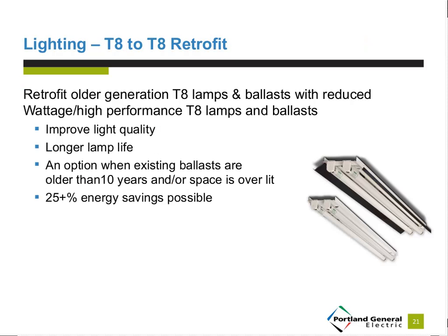Now this is where I talked about if your T8s are 10 plus years old, you can go to a high-performance T8 and ballast, improve your light quality, and get more hours. Like I said before, you can go up to 50,000 hours, where you'd be just getting up to 20,000 hours with a standard T8.